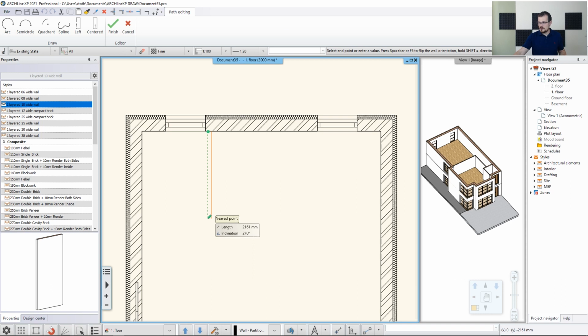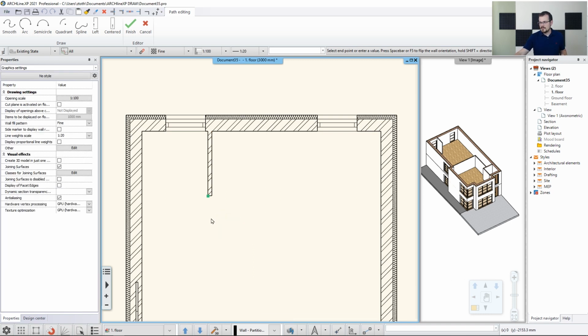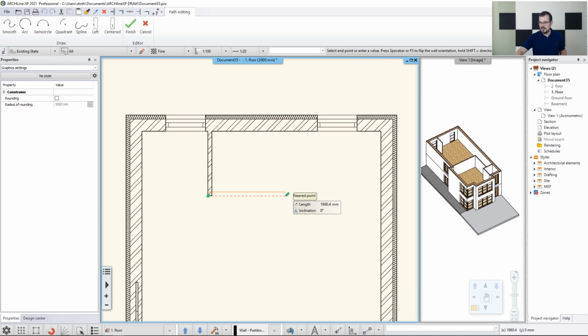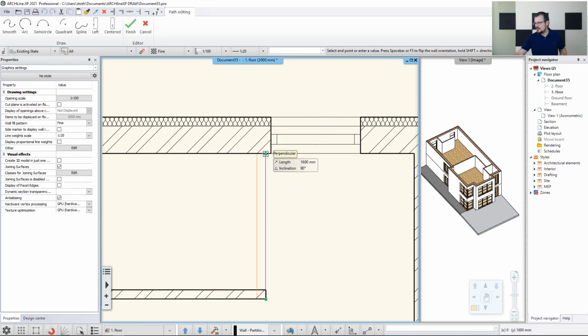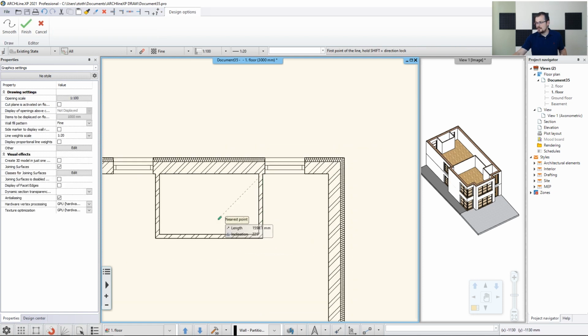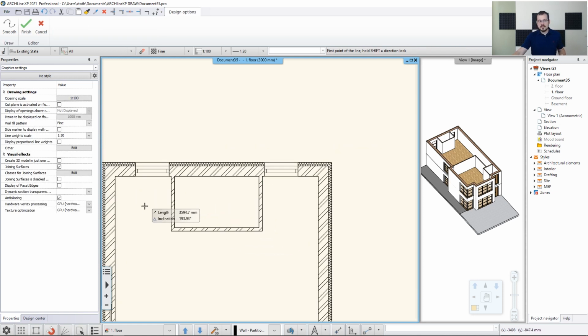I know that it goes downwards to 1,600, and then it goes east actually with a value of 2,700, and then it goes again up north. And this way you can create even symmetrical forms. So again, click on the point where you want to draw from, type in the value where you want to be when you start drawing, and then you just create the element.